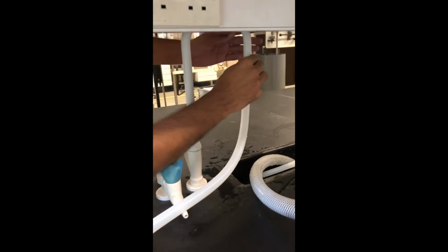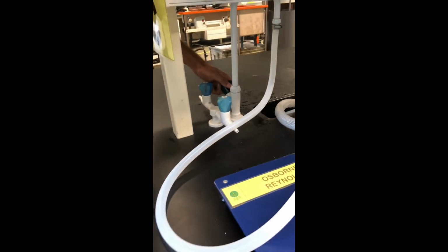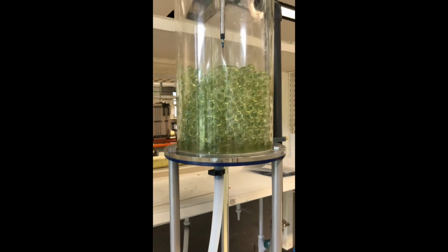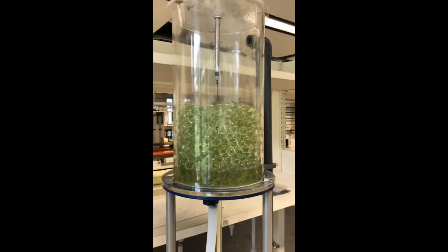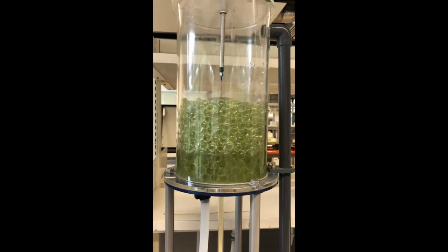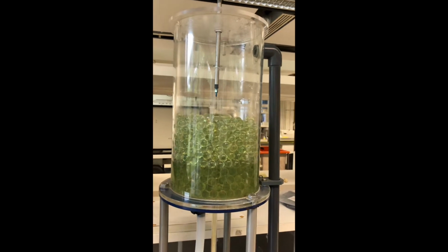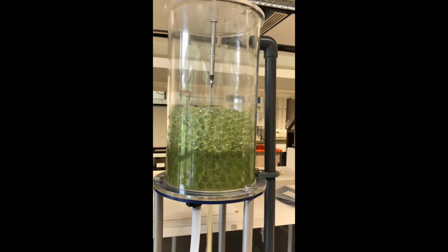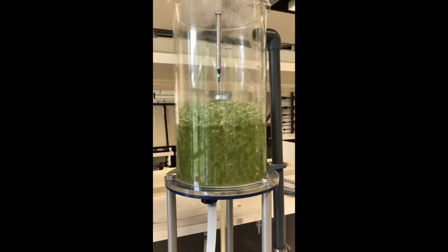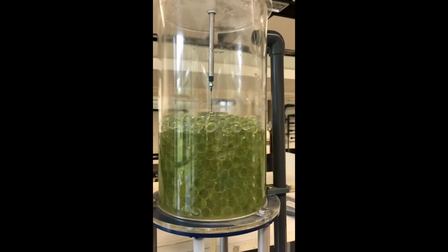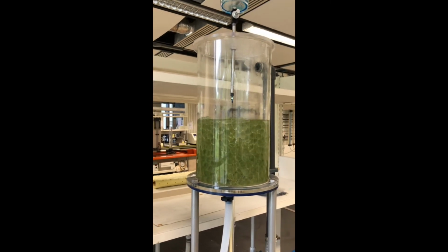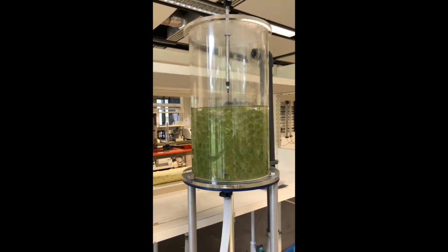Okay, now it's screwed on tightly and be sure of that. Now turn on the tap and let the water flow into the head tank. Now the water that has to be filled in the head tank has to reach the level of the overflow pipe. It is suggested that the water level be at such a level, with continuous flow coming from the inlet pipe, that a little amount keeps outflowing from the overflow pipe and a certain level is maintained in the head tank.